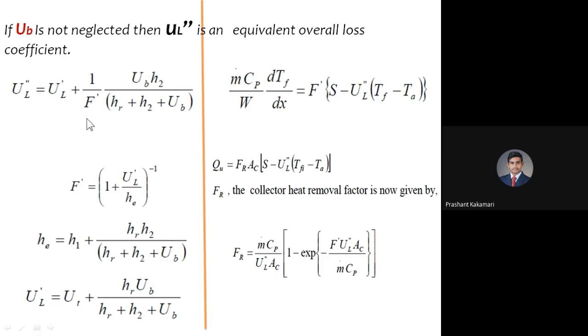So replacing this UL dash, or UL dash in other forms, like for example in this HE also. HE is the effective heat transfer coefficient, considering the heat transfer coefficient between fluid and the absorber plate, fluid and the bottom plate, the radiative heat transfer coefficient, and the bottom loss coefficient.